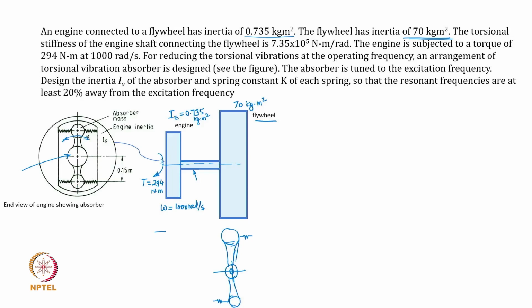So this bar is like in the slots of this engine or an extension of that engine, so that inertial mass swings about this axis, okay, and the oscillation of that mass or that link is restrained by 2 springs on either side, okay. So the moment there is an excitation in the torsional sense, the springs will try to resist and bring it back to its original equilibrium position. This is how the absorber is to be designed.